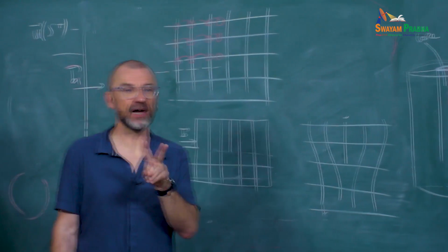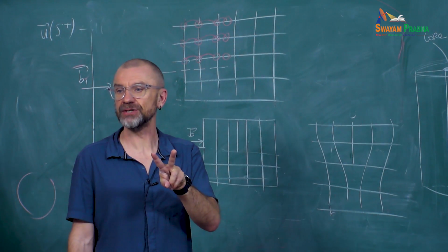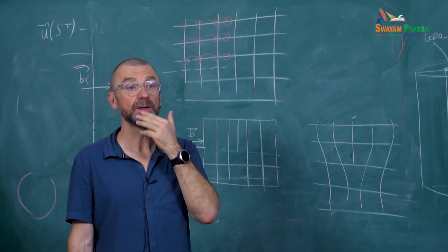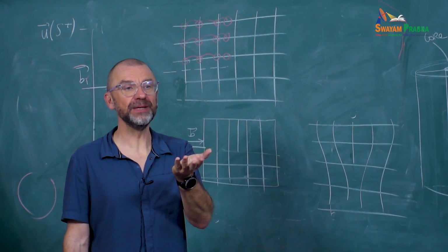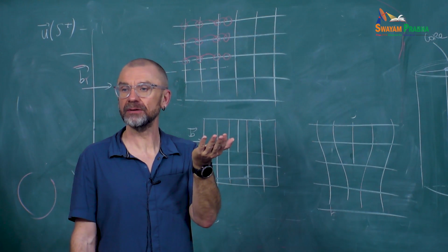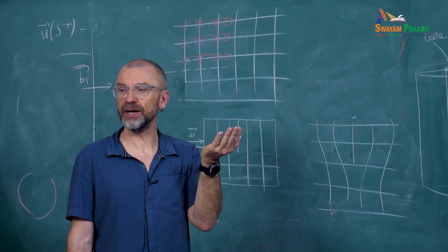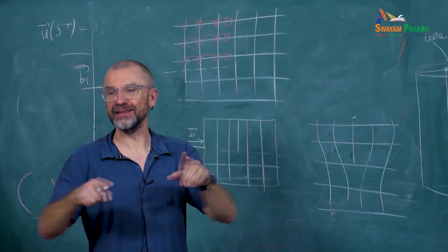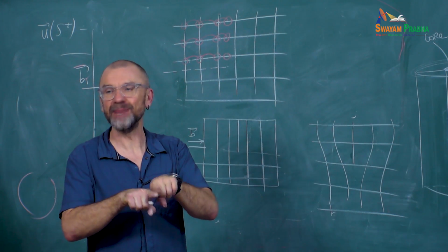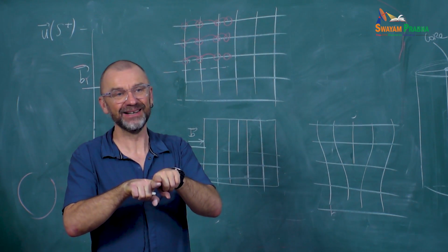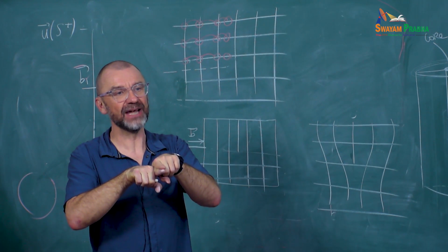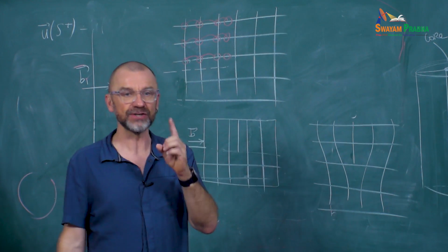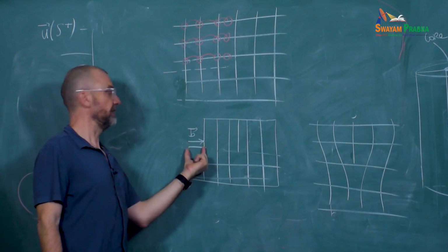So there's going to be two extra half planes. What will be the Burgers vector of that dislocation? It's going to be 2b. So what will be the energy of that dislocation? 4b squared. Now, if I look at the dot product of b by b, it's always positive. So that 2b dislocation will be unstable with respect to dissociation. And so I'm going to go back to a Burgers vector which is equal to the interatomic distance.